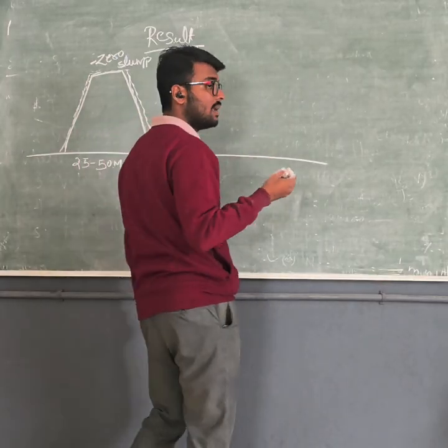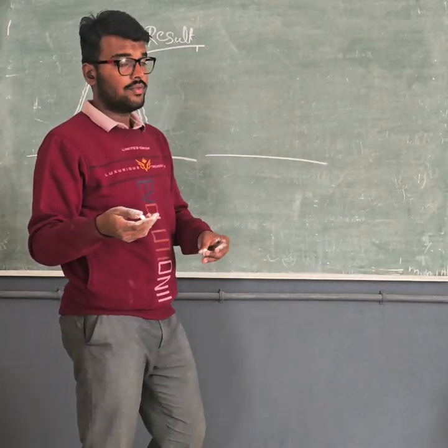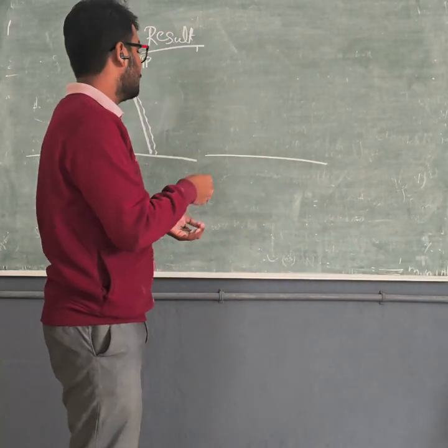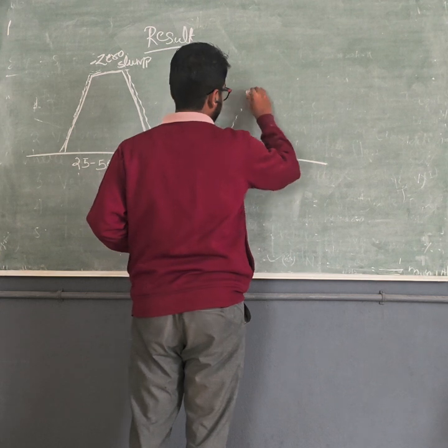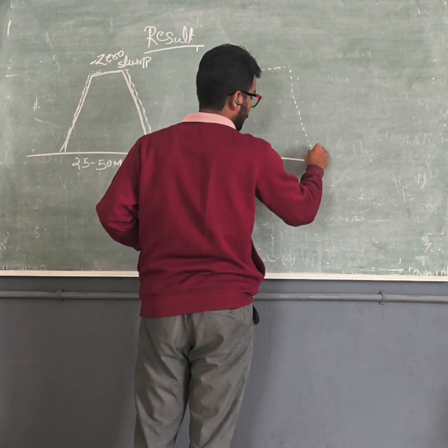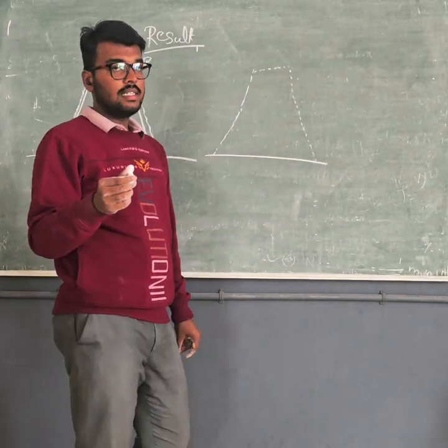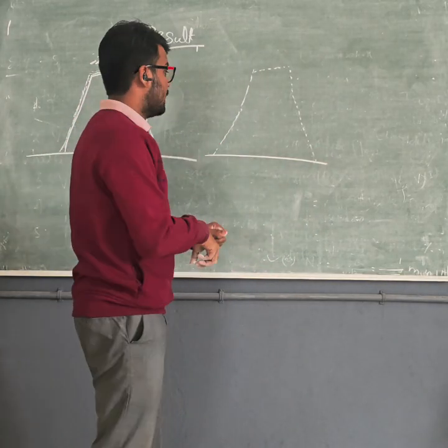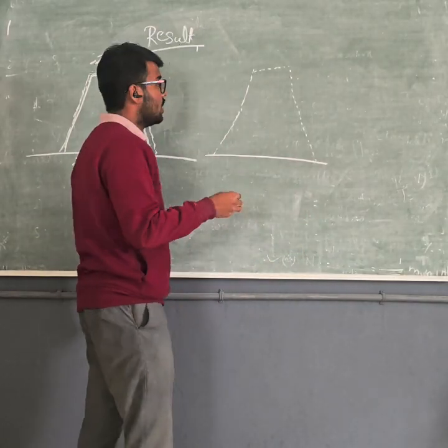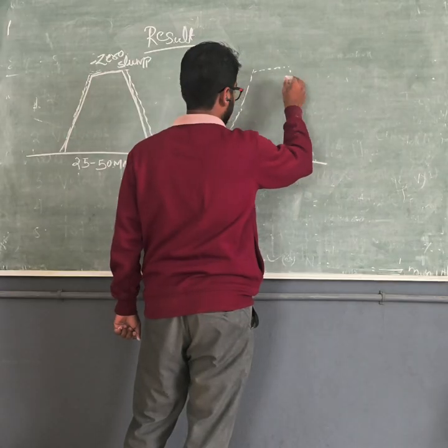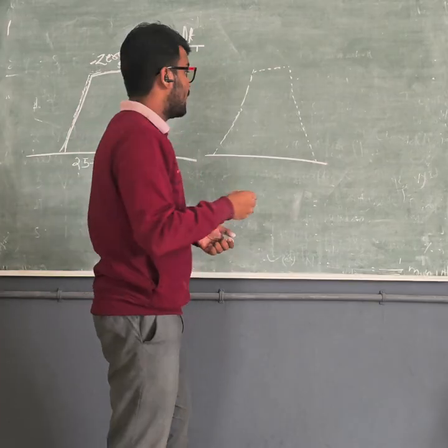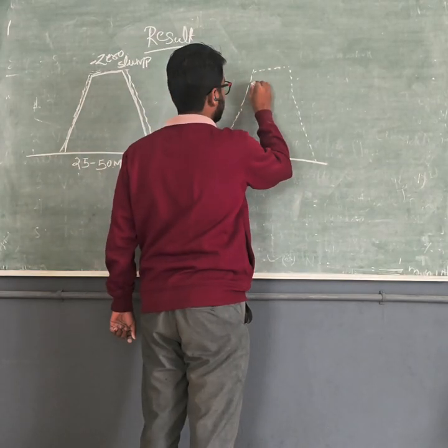true slump, which we usually find on site. How do we know whether this is a true slump or not? After removing the mold, the specimen should shrink. The specimen should have shrunk in height, and it looks like this.